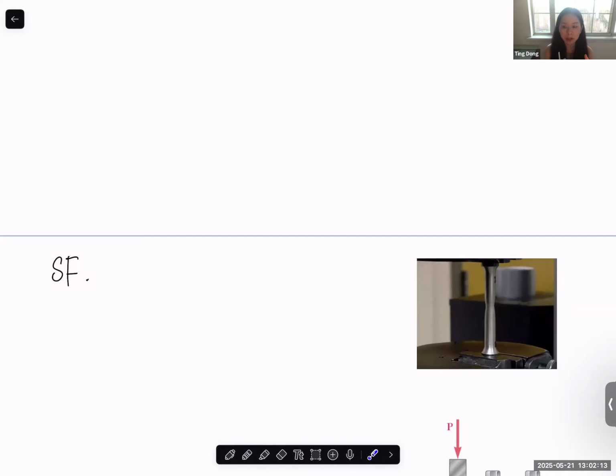And also when we design a bridge, we assume a maximum stress caused by different cars driving on the bridge. But what if in one day there's a huge truck with a very heavy load driving through? There's some uncertainty in the force applied to your structure also. So to accommodate those uncertainties, we normally put in a safety factor, which means there's some margin.